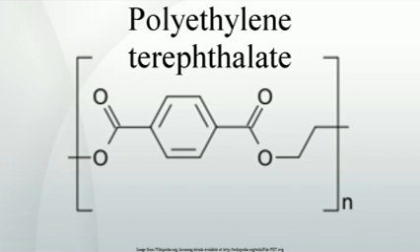Partial glycolysis. Partial glycolysis, transesterification with ethylene glycol, converts the rigid polymer into short-chained oligomers that can be melt-filtered at low temperature. Once rid of the impurities, the oligomers can be fed back into the production process for polymerization. The task consists in feeding 10 to 25% bottle flakes while maintaining the quality of the bottle pellets that are manufactured on the line.